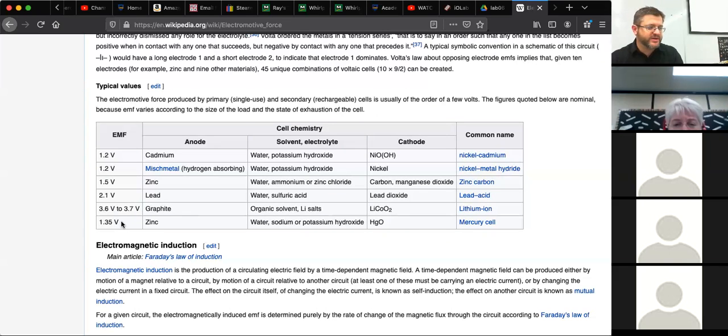So for example, one of the reasons that we like lithium ion cells, which are these ones right here, is that it's rechargeable. It maintains its integrity charge after charge after charge. It's very easy to keep this battery clean in its reactants. The downside of lithium ion is it creates a lot of heat, so you have to dissipate that heat constantly. If you don't, it will actually outgas. Some of this stuff will turn into gas, and then it'll swell up and explode.